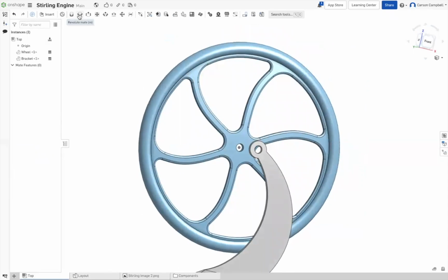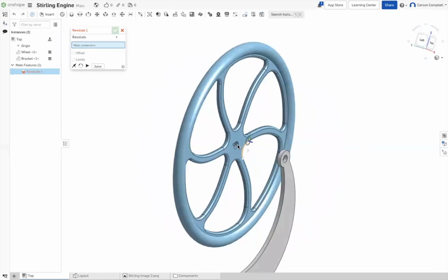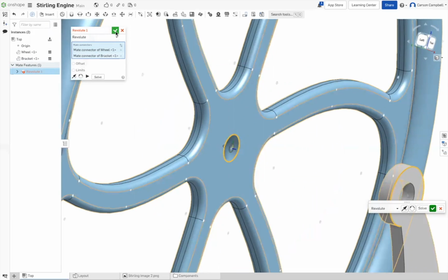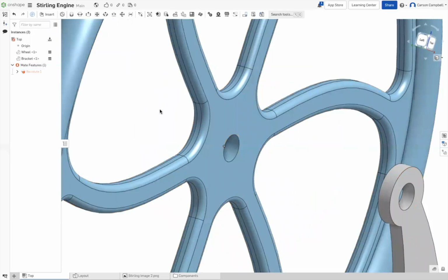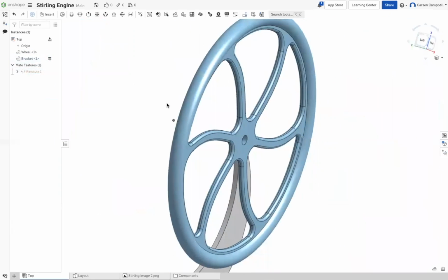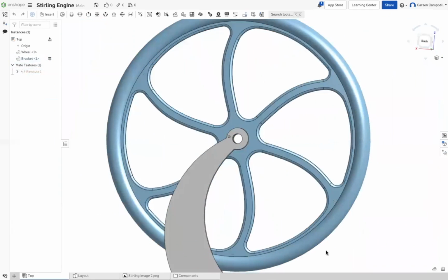All right, so you're getting there. Okay, go for it. It failed. Yeah, that's because, hold on here. Let me ask you a question. You want the wheel to rotate, but you also want to fix it. Okay. Turn the fix off on the wheel. Go up, right mouse click, say float, unfix. All right, that's fine. You want to offset the, yeah, there you go.